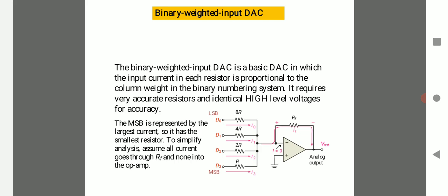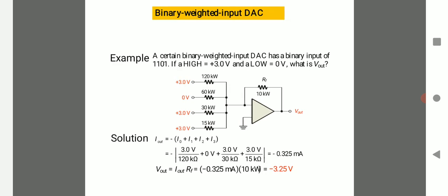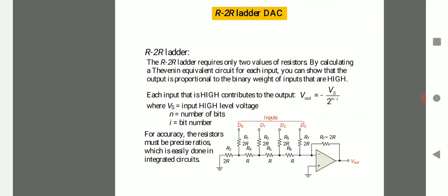This has a wiper terminal like the basic potentiometer, which is replaced by a single rotary switch connected to each junction of the series resistor chain. You can see an example of this. If you give a certain amount of current towards the voltage for the digital circuit, the potentiometer is replaced by the single rotary switch, and this forms the basic potential divider in the circuit. As the switch rotates from one position to the next, the output voltage changes quickly in discrete, distinguishable voltage steps. This can be used for 2 volts, 3 volts, 5 volts, and also for 2.5, 3.1 and 4.6 volts.